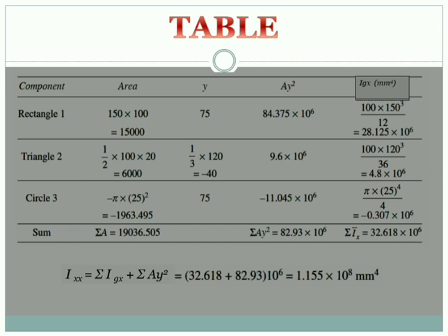Why does the moment of inertia carry a negative sign? Because that much of the mass is removed. That much of the mass does not exist in the system, so we cannot add that to the Igx summation. That much of the mass is removed from the system, and mass is directly connected with moment of inertia, which I have explained in your first introduction chapter of moment of inertia. So here we get the answer of Igx as minus pi into r raised to 4 divided by 4. Then we will get the summation of Igx.